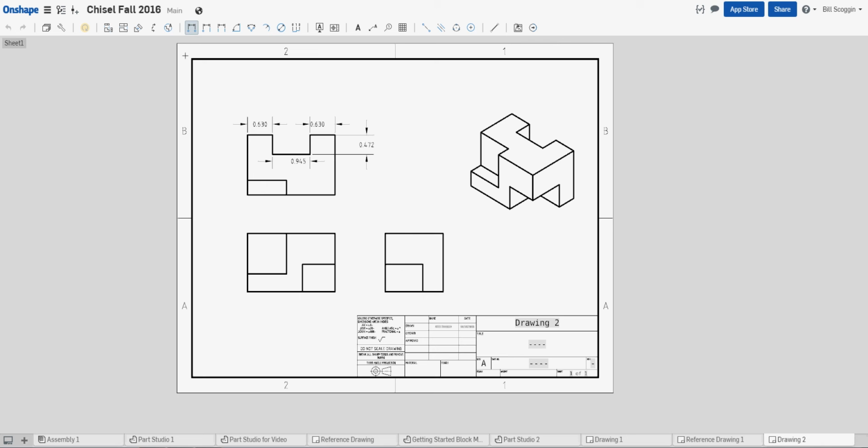And my lower left pocket. Notice I do not have to keep hitting the dimension command every time. Also, I'm going to kill the dimension command by hitting escape. I'm going to turn show hidden lines on for each object. I have to select them individually and then select the next one. I haven't figured out how to do them all at once and get it right.